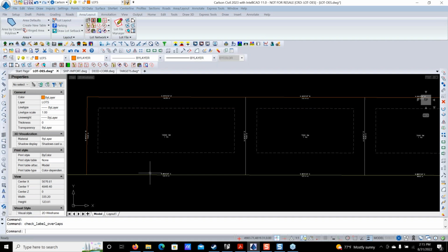And then I talked to them again, and they changed their mind. It's very unusual, but they said, here's what we actually want to do. I'm going to draw a polyline, and I'm going to come across here, and then I'm going to use a nearest O-snap. I did a nearest at the beginning, and I'm going to O-snap over here. And that's just a polyline, folks. That's just a 2D polyline. I can show you that with Drawing Inspector.